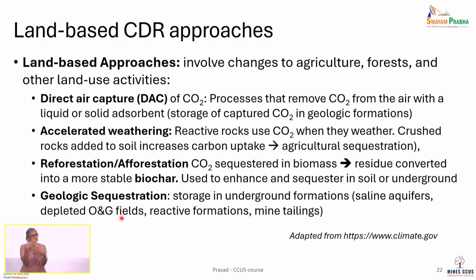That 500 psi after we produce is the window of opportunity for us to pressurize it again over 10, 20 acres, thickness of 10 feet, maybe 20 feet, 100 feet is even better, and a porosity of 20%. We can do the math, and we'll do that in class next week. We will calculate how much capacity you get if you have a pressure differential of 500 psi to work with. Usually we don't have the luxury. Usually we have only a few hundred psi that we're working with.